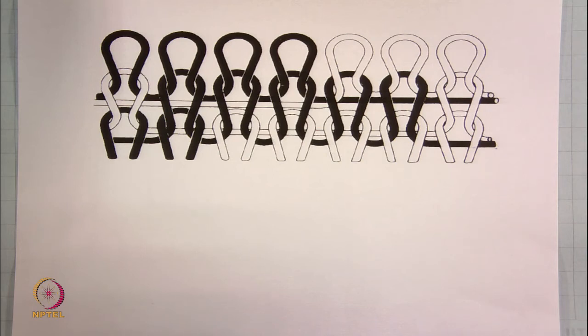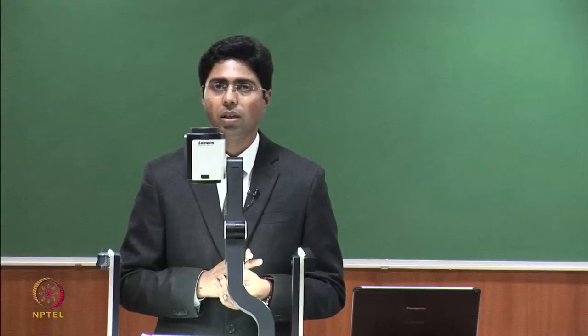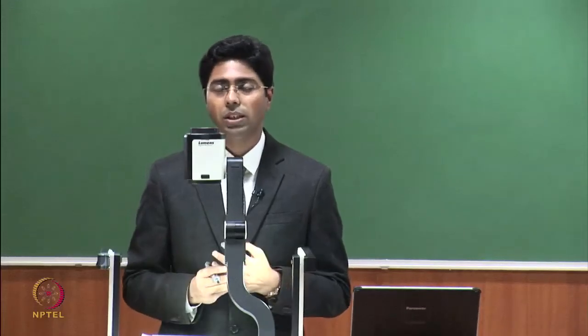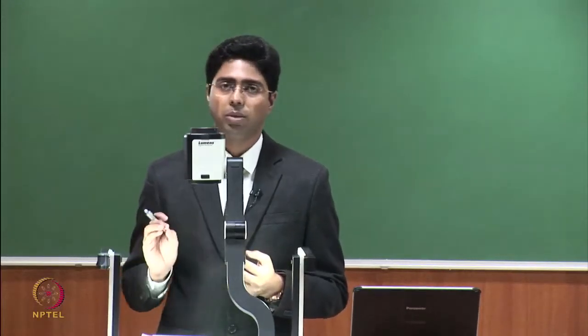We have such technologies, jacquard machines, which I will be covering later in this course, where you can individually select and give yarn to each individual needle. Every time you can change the yarn feed and select each needle of the bed individually. That is an even more complicated technology, but let us first focus on the fabric notation of this particular fabric.